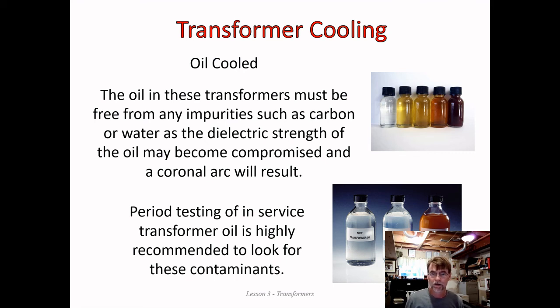All kinds of different cleaning was required, and testing was done, and one of the things that was always done was to take a sample of the oil. The oil goes away for testing to determine its dielectric strength. If it's found to be degrading, then you might have to add to next year's maintenance schedule the replacement of that oil. Part of the annual maintenance would be to actually drain the oil out of the transformer and replace it with new clean oil.